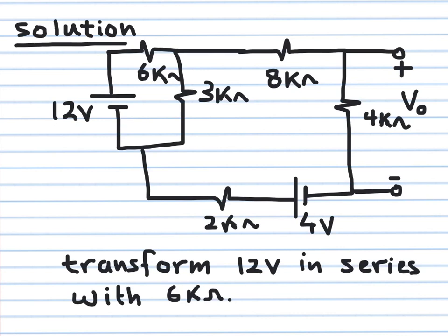There is a resistor here called 6 kilo ohm, and it's going to be in parallel with a current source, and this voltage source is gone already. So this voltage source is gone, this resistance is gone, and now I'm going to combine this resistance because they are in parallel, and I'm going to convert this one back to another voltage source.